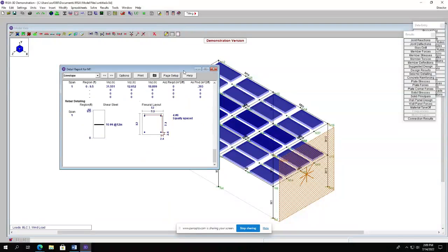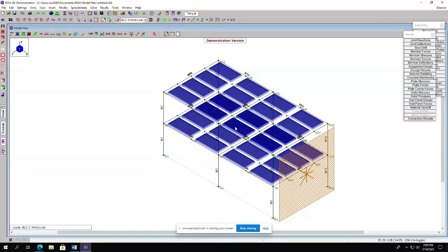So the first step that we did was creation of the model over here. We created our model using the grids. After that, what we did is we assigned the loads. There is a little toggle between the model selected and unselected. After assigning the loads and members, we put the loads on the members, on top of the slab, and the wind loads and everything. So if you've got the seismic load, you have to do that as well. After that, we ran the model from here.